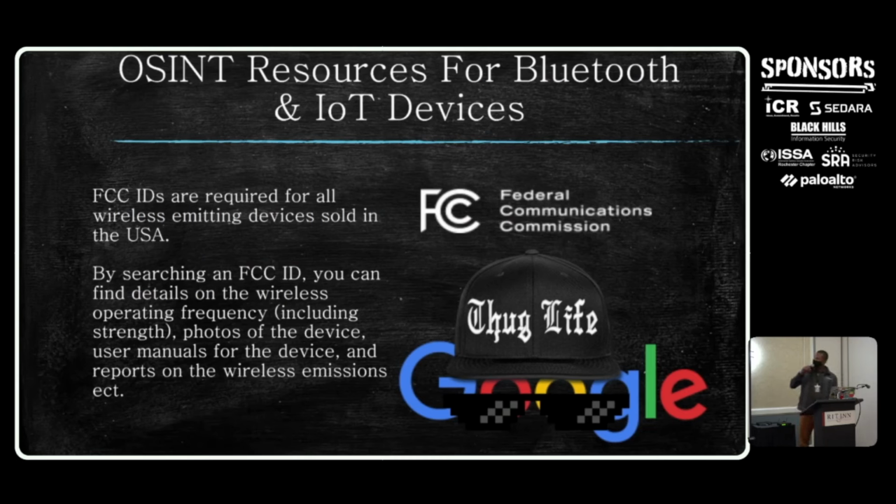All right, so more about these open source intelligence resources for Bluetooth and just devices in general. One of my two favorite resources would be the FCC directly, along with Google. And you can find this one website, fcc.io, through Google search. And as it states here, they are required for all wireless emitting devices sold in the United States. And honestly, you can get a wealth of information, internal and external diagrams of the device, where you can take a look at the chips if you want to do any desoldering or anything along those lines. But fcc.io is a great resource and will have a surprising amount of information.